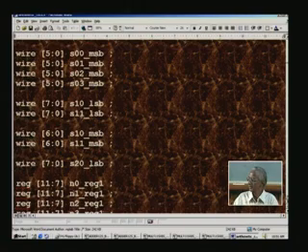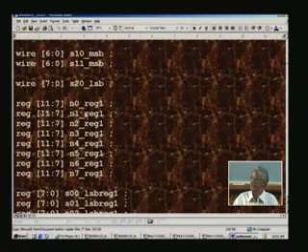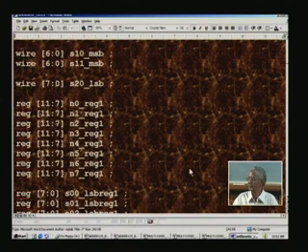And there are also numbers N0 through N7 which will have to be propagated, which are not computed at a particular stage. For instance, the MSB has not been computed, therefore they have got to be registered and propagated through the pipeline in order to be processed when the time is ripe.